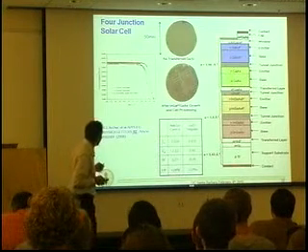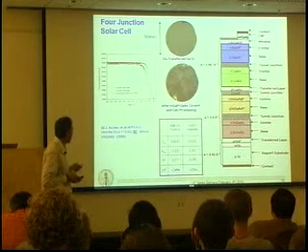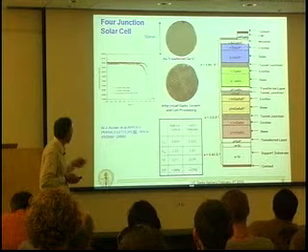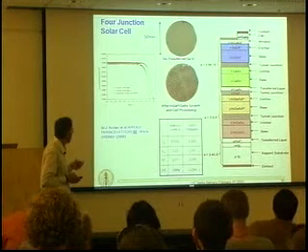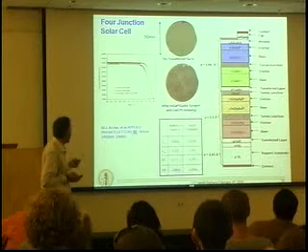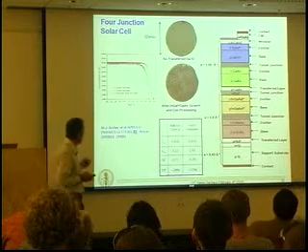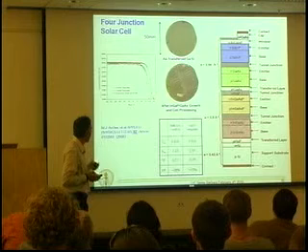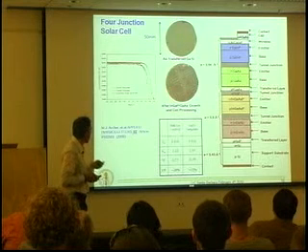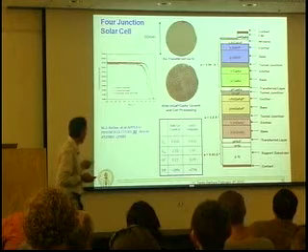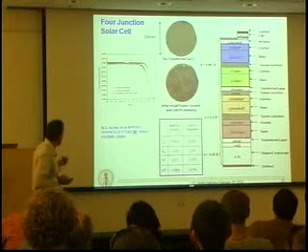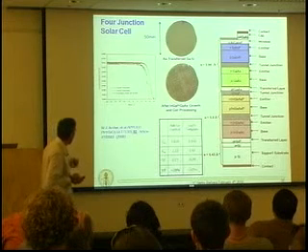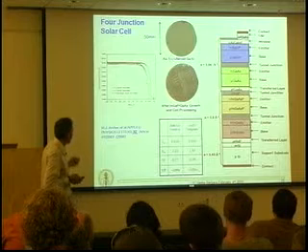Here are some examples of multi-junction solar cells that are made on silicon in our lab. And these are experimental results for the top two cells here, a gallium arsenide, gallium phosphide cell. And these are made by a process where we start with a silicon wafer, we peel off germanium in a thin single crystal film, transfer it onto a silicon wafer, then grow on this germanium template on silicon, gallium arsenide, gallium phosphide solar cells. This shows the cell conversion efficiency, and there's a little bit of a difference in the open circuit voltage of the cells. But basically, the message is that these are comparable in efficiency to cells grown on bulk germanium substrates.